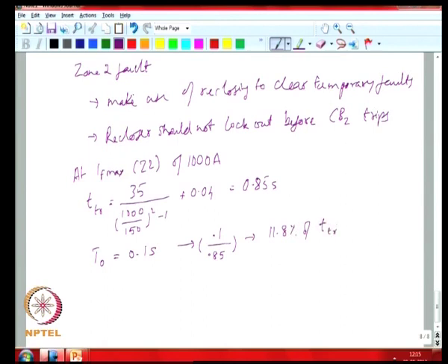So, it is about 11.8% to trip at that particular condition, and then you have the first off duration T off 1 of 5 seconds, and the 5 seconds in terms of the overall reset time for the circuit breaker, which is 30 seconds, means that it is resetting by 16.67% of T reset. So, obviously, it is not going below 0, so it now resets back to 0.